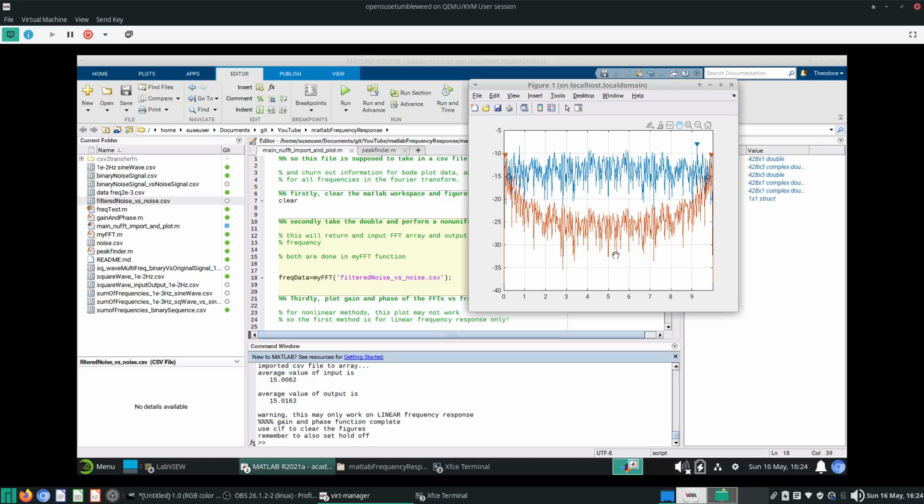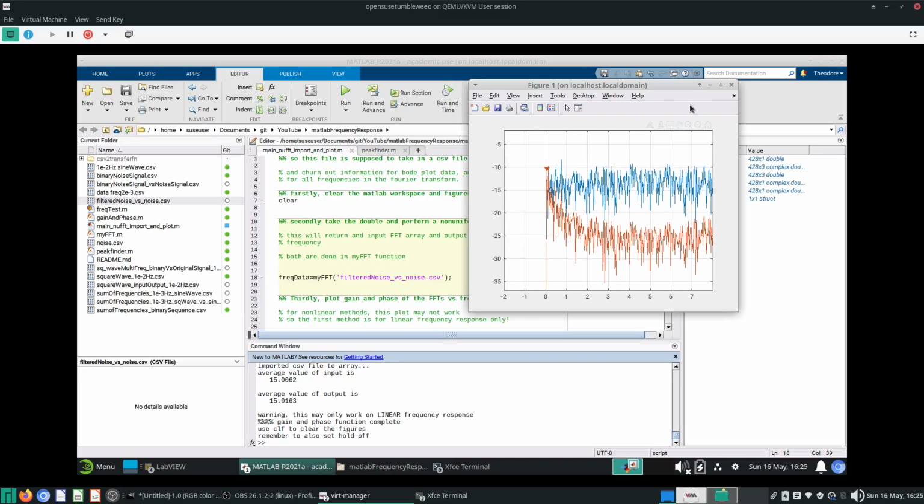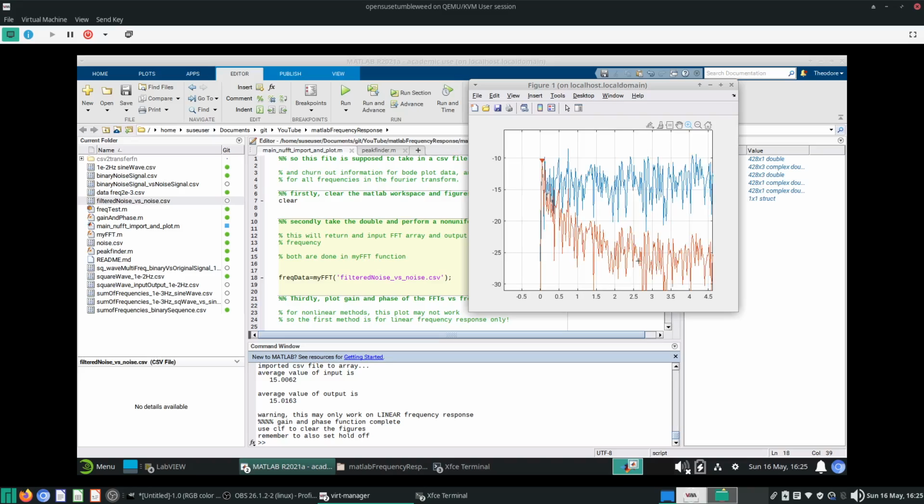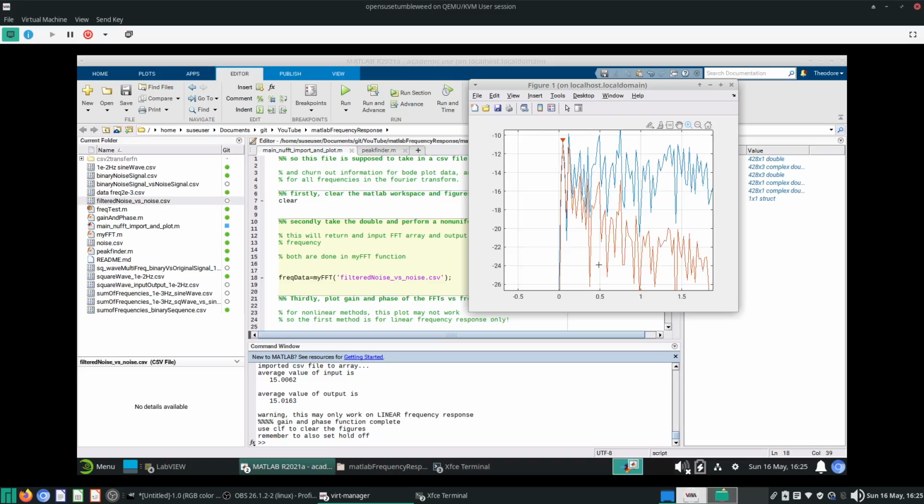Of course, this Nyquist frequency is actually 5 Hz because we are sampling 10 samples per second. So that's 10 Hz, and 10 Hz divided by 2 is the Nyquist frequency, 5 Hz. So you can see what this low pass filter actually does. This is one way of generating an input where you want to focus on a few frequencies.